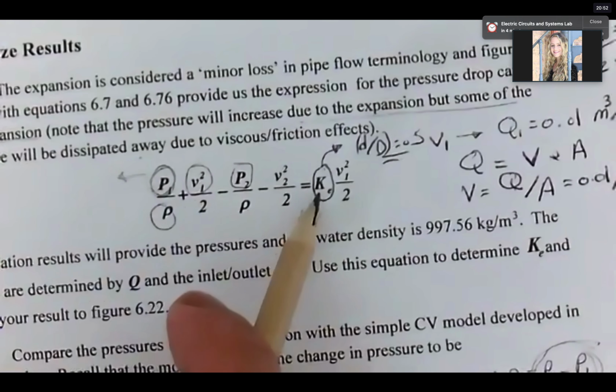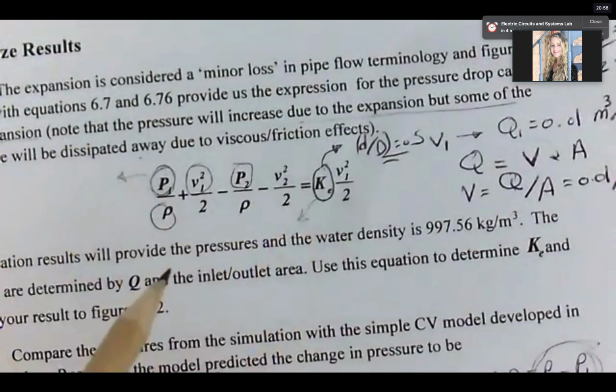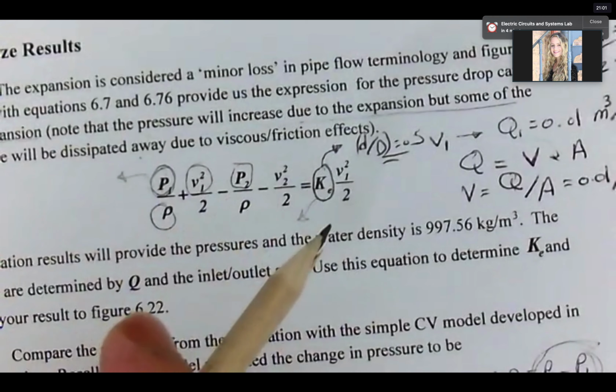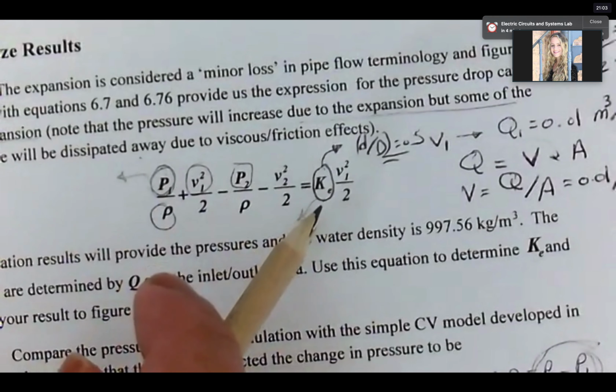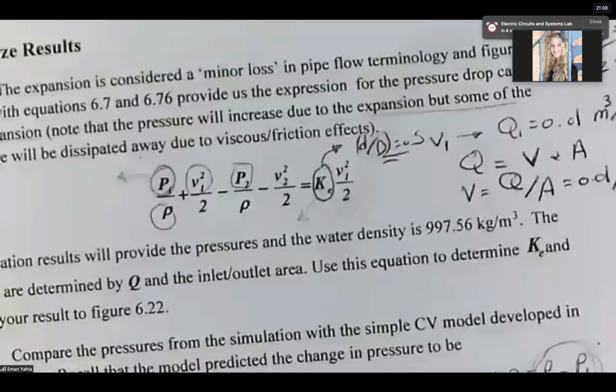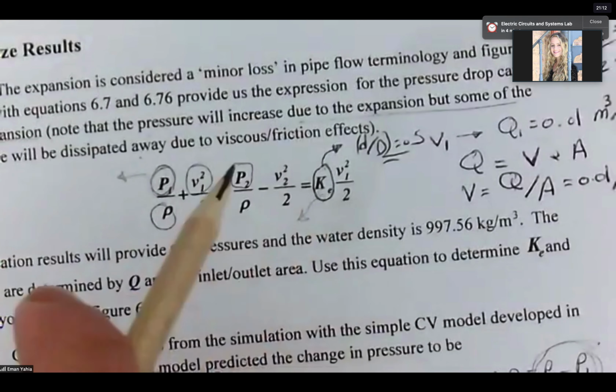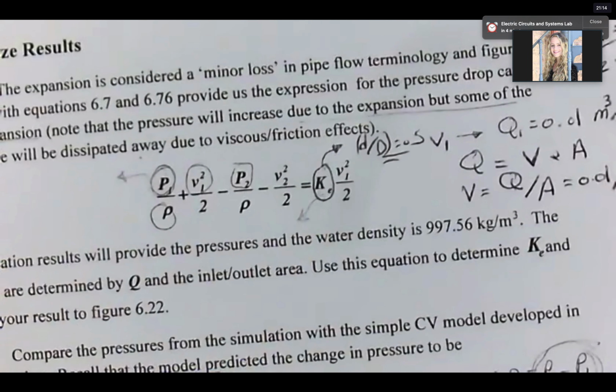But if you get K epsilon like, let's say, -5, and he's supposed to have something between 0.5 and 0.6, in this range, right? If your output or what you calculate doesn't make sense, that means even if you see the simulation and you feel like it's good, something is still not correct.